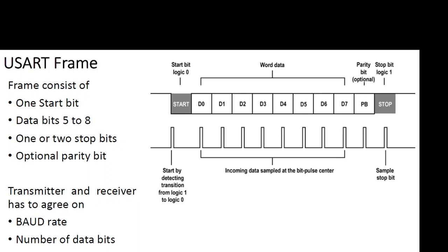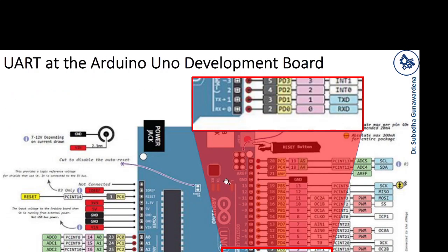So this microcontroller has one hardware serial port which is attached to the second and third pin of port D. Let me see if I can get an image. So you can see here, the serial port is pin number 0 and 1 here. So pin number 0 and 1 in the Arduino Uno board. So that is again pin number 0 and 1 of port D.